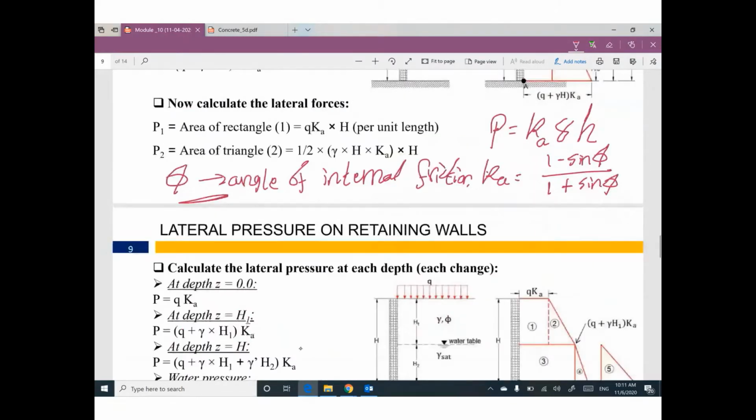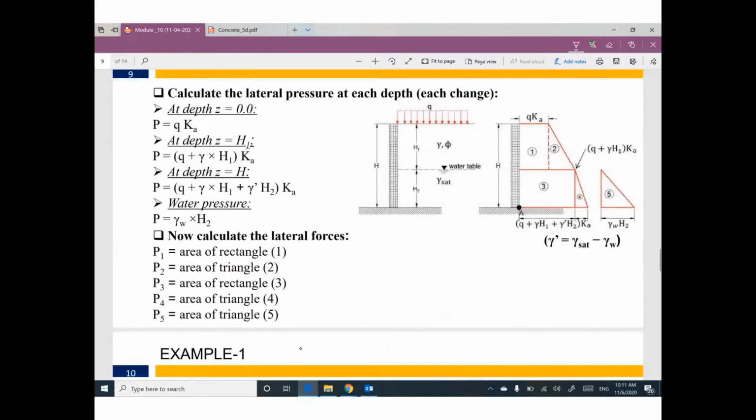I need only to highlight something here, and I will start with an example. If you have water table, sometimes we have underground water. If you go back to hydraulics, this water will cause a triangle pressure, and the pressure here equals gamma water times H. At the water table surface, we don't have H for water, so your value here is 0.